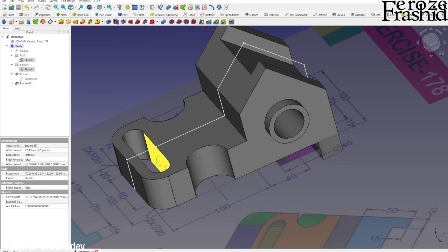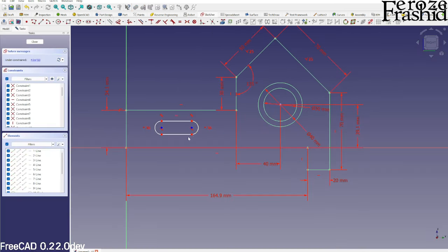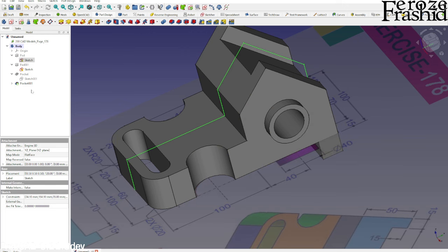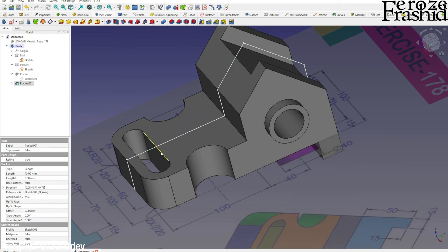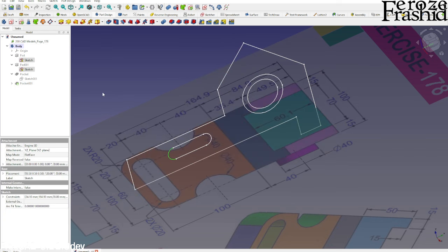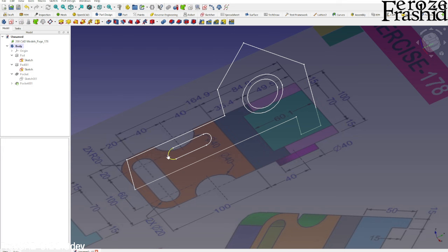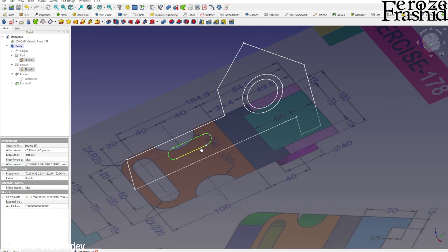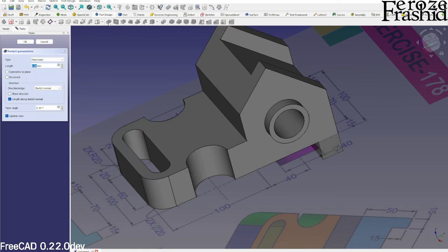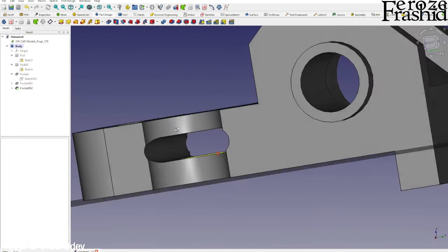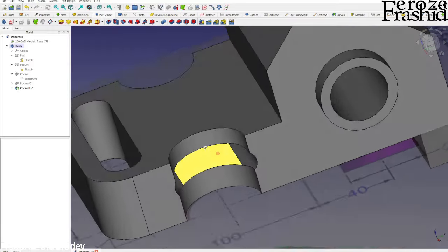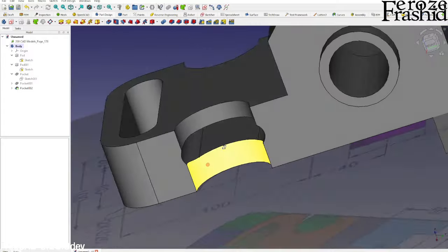Okay, it's showing up in the wrong place. Let's go back, maybe put it in here, right? And then what I want to do is find that here, and then select this and make a pocket through all, symmetry to the plane. Great, it worked. So this is awesome.